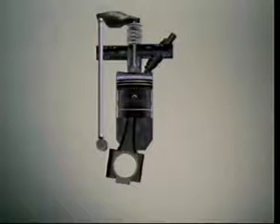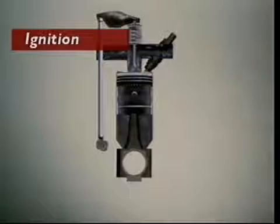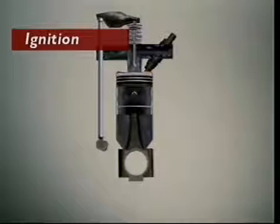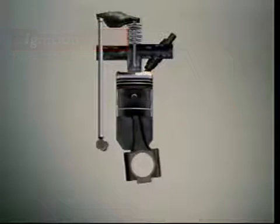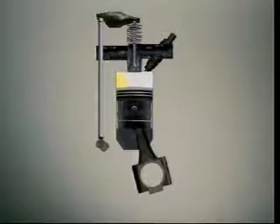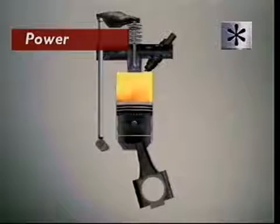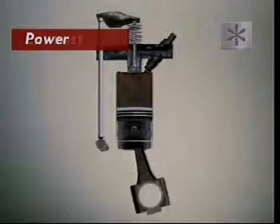Just before it reaches top dead centre, an injector sprays fuel into the chamber. It mixes with the very hot compressed air and ignites. Combustion occurs. The temperature rises much higher and the gases expand and force the piston down in a power stroke. The piston reaches bottom dead centre.